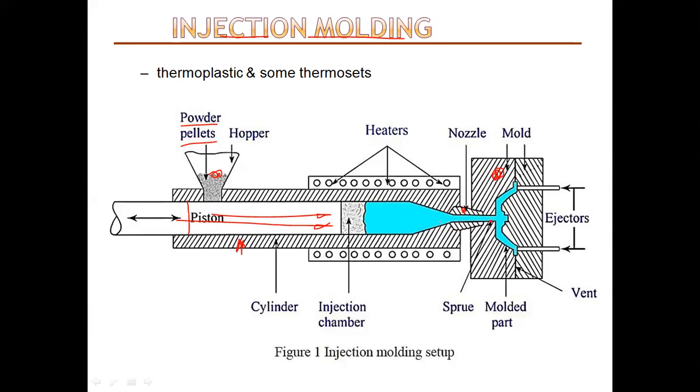The pressure is maintained for a short time to prevent the material creeping back during hardening. This prevents shrinkage and therefore gives a better quality product.